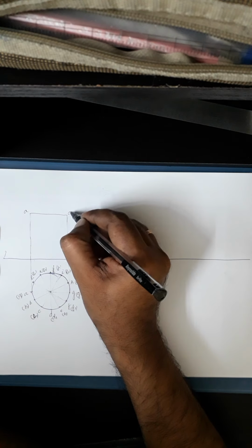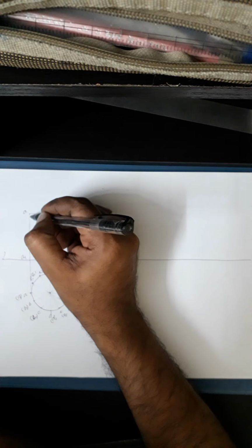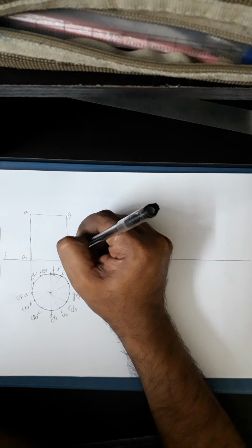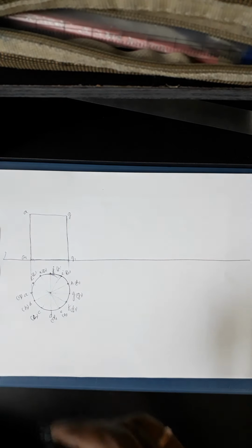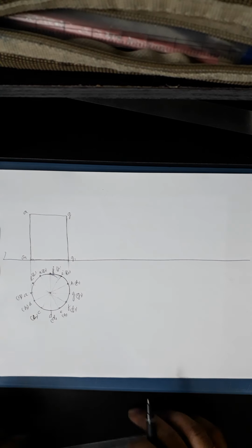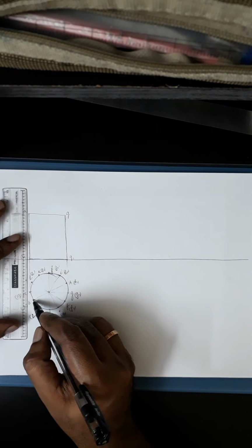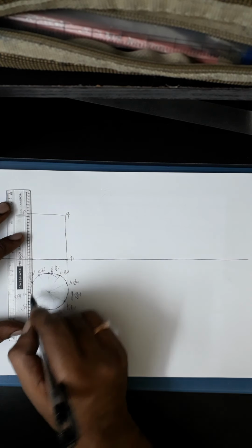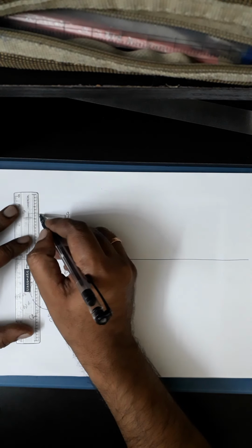So this is A, this is G, this is A1, and this is G1. Then the generators will be drawn, because there is the boundary line, so will be marked with HB pencil, whereas all others will be imaginary, so let it be thin. In that case we are going to project all this now. So B and L will be coinciding, okay, then C and K will coincide,